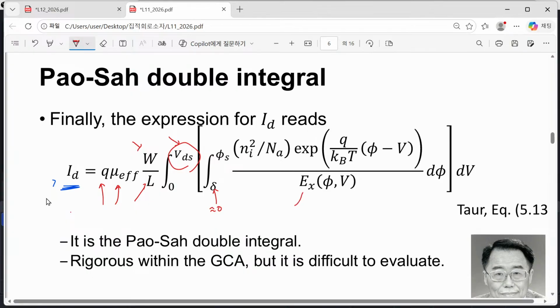And you know the form of Es and ni, the intrinsic carrier density. Also, you know this value at 300 Kelvin. It's about 10 to the 10 per cubic centimeter. How about Na? This is the doping density, and you know the substrate doping density of your transistor. This is the summation variable, and these are just integral variables.